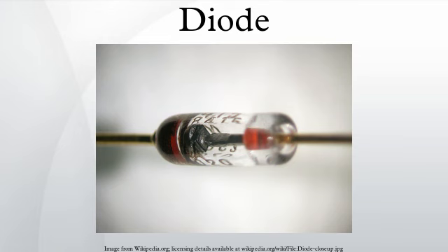Photodiodes. All semiconductors are subject to optical charge carrier generation. This is typically an undesired effect, so most semiconductors are packaged in light-blocking material. Photodiodes are intended to sense light, photodetector, so they are packaged in materials that allow light to pass, and are usually PIN. A photodiode can be used in solar cells, in photometry, or in optical communications. Multiple photodiodes may be packaged in a single device either as a linear array or as a two-dimensional array. These arrays should not be confused with charge-coupled devices.